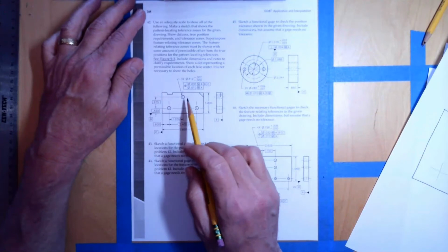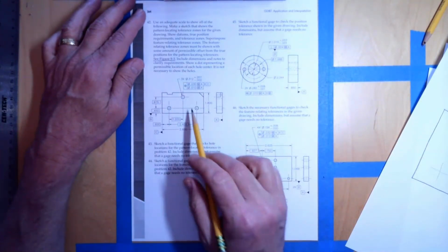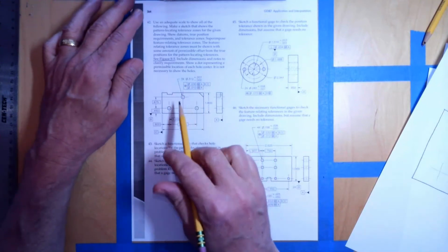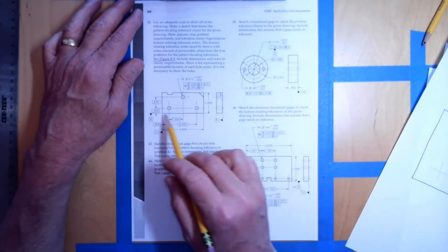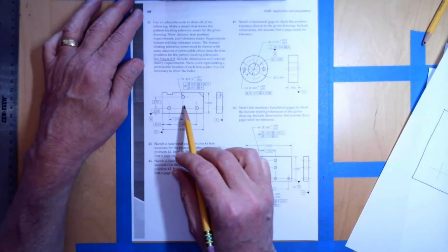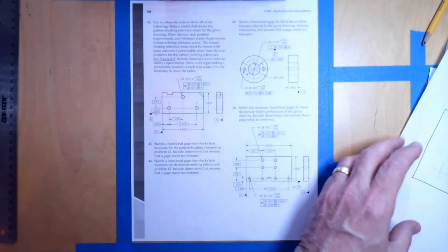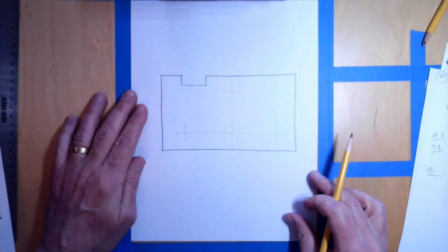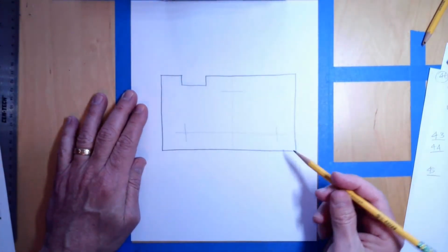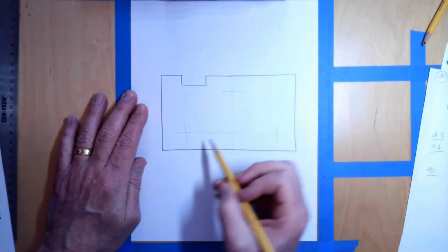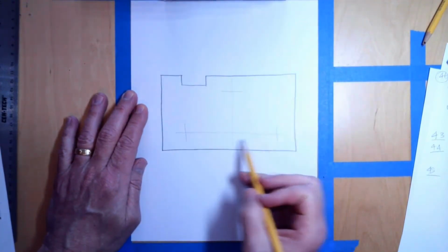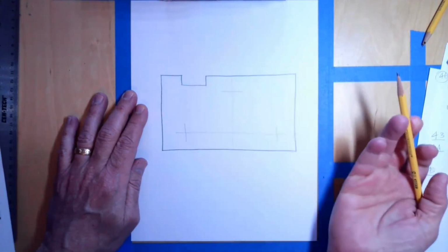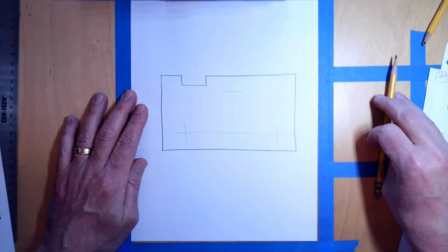So what we're going to do is we're going to mark out, basically, we're going to locate these tolerance zones on a superimposed figure of the outline of the part. All right, so here we go right here. So here's the outline of the part, and you can see I have a very light sketching of the center of the holes, which we'll use for the pattern locating tolerance zones.